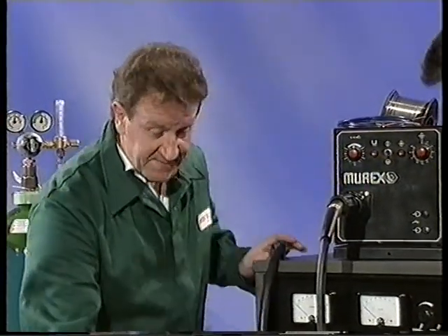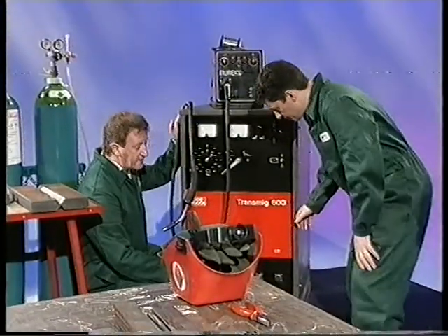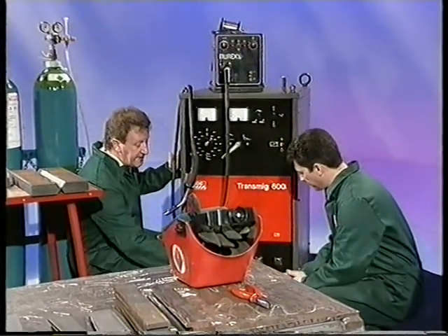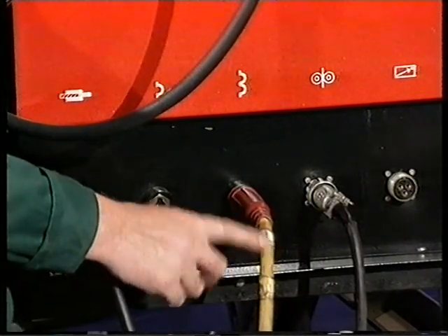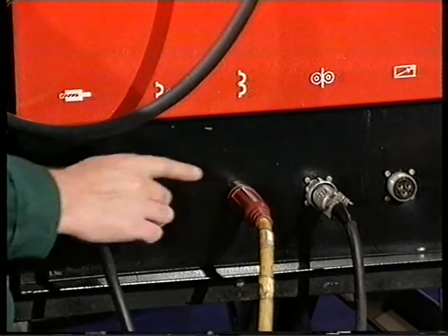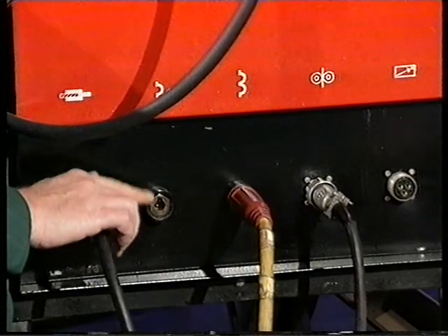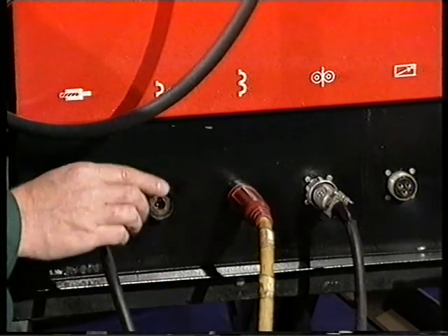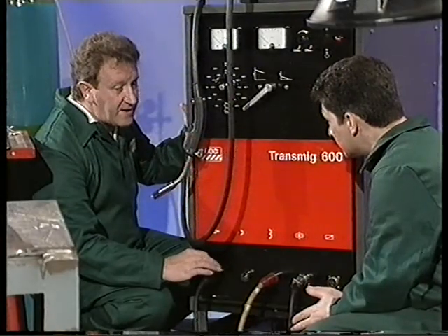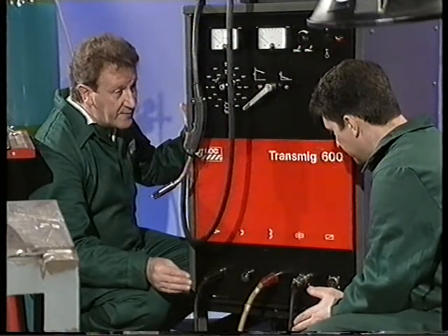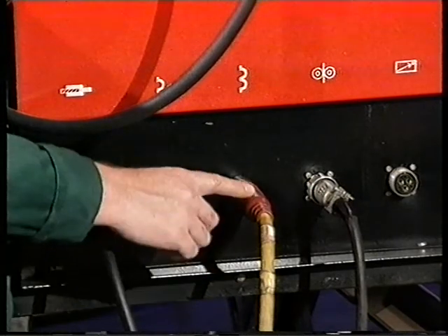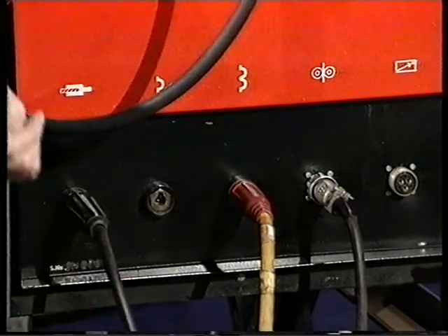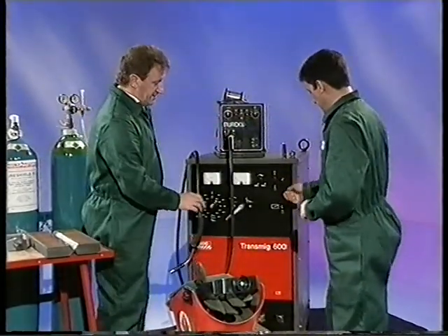The power cables themselves, we have the earth return lead going back into the machine, and here this lead is taking the welding power up to the wire feed unit. You can see there are two inlets for this. This is the inductance, and this is of importance in dip transfer in that it determines the amount of time that resistance heating is allowed to build up in a wire before it necks off. For this particular application, I think we'll probably be best on that inductance tapping. Right. Okay, so we power up.